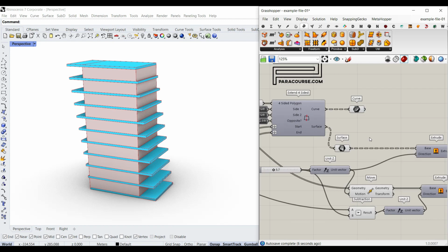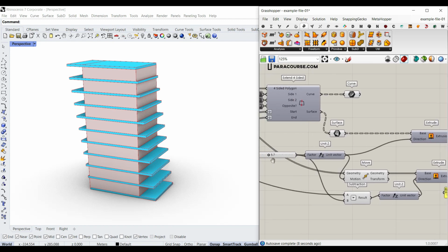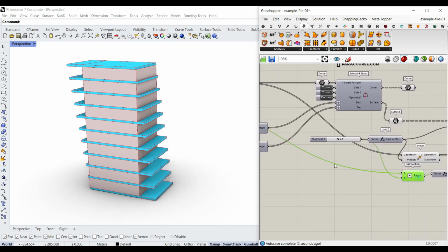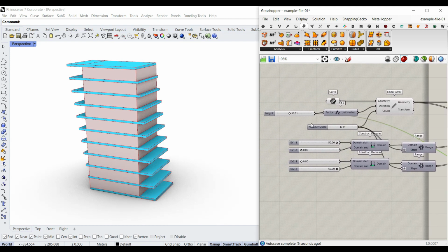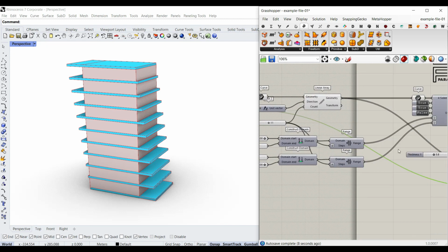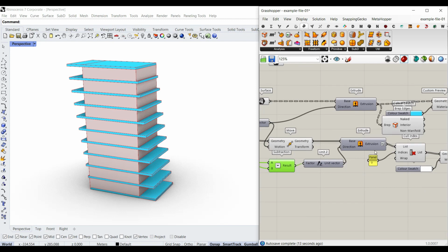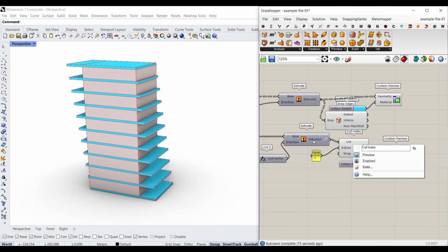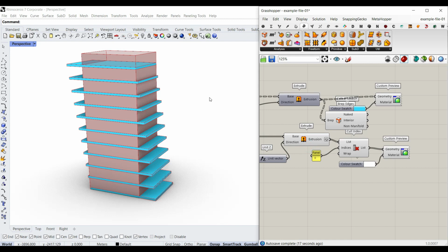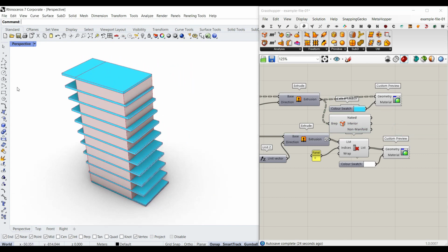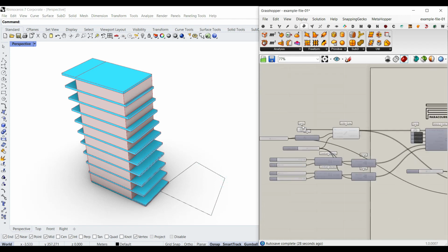And that's it. After we have the surface, we have extruded that for the thickness we need here, and the minus is going to be the subtraction of the height and the thickness of the roofs. So you can see we just move them up, we extrude that and delete the last part because we don't need this last part, and you can just see we have a simple custom preview with some edges. And now we can just give any four-sided polygon to the input and get new results.